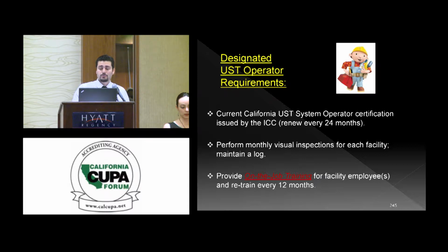Was it a simple issue like rainwater going into the sumps and causing a turbine shutdown or an alarm, let's say? Or was it more serious, like a potential release of fuel for whatever reason in piping and a compromise in the piping? So we need to ensure that those alarms are checked out.